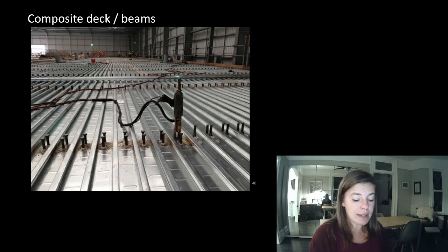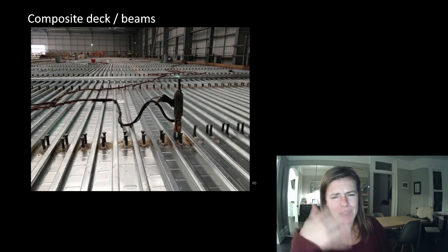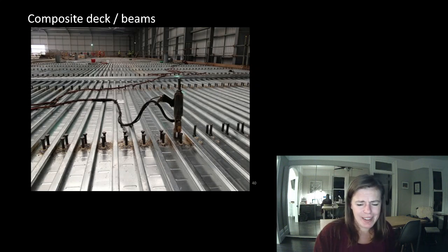And if we can say, oh, well, this is an application where nobody cares. It's not something precious. It's not an office building. People aren't sitting here doing math all day. They're people kind of walking to and from to get something very specific. Maybe it's an industrial application. In those situations, it might be worth saying screw it to the vibration criteria and saving the money on the steel.